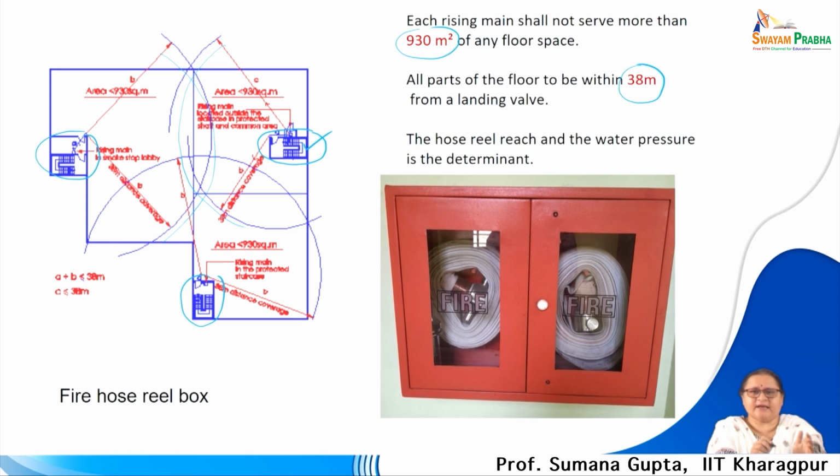As you can understand, these are very large sized floor plates. So, we are talking of commercial buildings, office spaces, high rise buildings, where the spread of the building is quite large, the floor plate area is quite large. And you can see here through the demonstration, which is taken from the National Building Code, that the spread is quite important in deciding how many staircases to put.